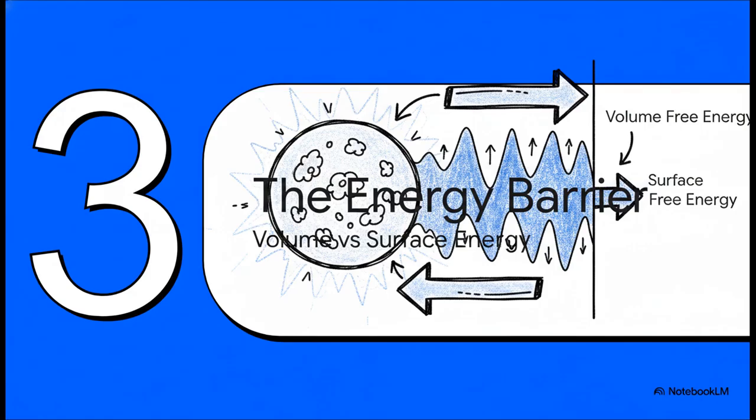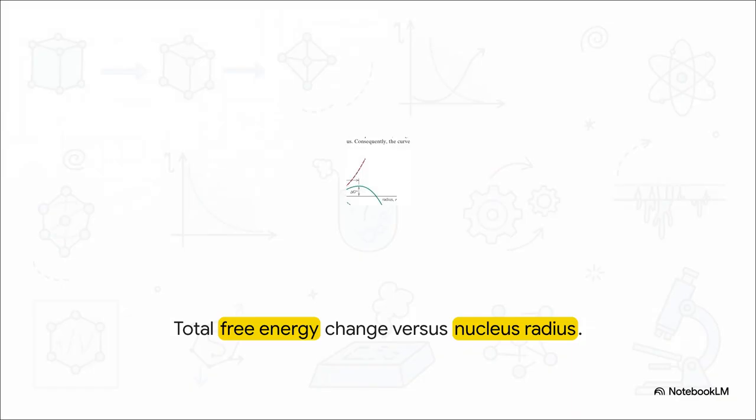Moving right along to section 3, overcoming the energy barrier. Now, what's really interesting about this is what happens as our tiny cluster of atoms actually tries to grow into a solid. It gets pulled in two entirely different directions by competing energy forces. On one hand, volume-free energy pulls it forward. That's what actually drives the transformation. But on the other hand, surface-free energy holds it back, because creating a brand new physical boundary between a solid and a liquid requires a lot of energy.